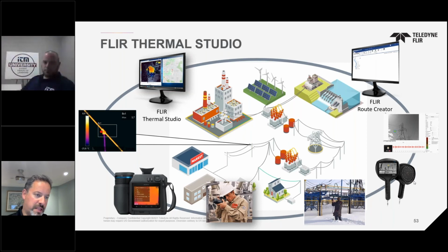If there's no pressure, if the gas or air in the piping is at the same pressure as the outside, there are no vortices being made, there's no ultrasound, so the camera will not pick it up. If it's a small leak but under higher pressure than atmospheric, where it creates that push and those vortices, the camera will pick it up.